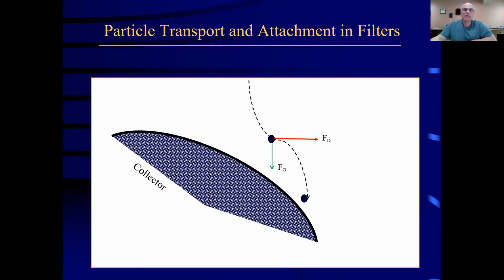Another arrow, another vector working against you, would be the electric double layer that exists between all particles in suspension. This electric double layer is what helps keep things in suspension, helps make suspensions of particles. And our job is to get in and get that very stable suspension that exists in Mother Nature and destabilize it. If we can destabilize it, we can strip away or at least make that arrow smaller so that it doesn't work against us. If we don't destabilize that water, those forces are going to work against us and make it very difficult for these particles to ever settle. In fact, true colloidal particles will suspend themselves in water and stay there for a very long period of time. We're talking days and weeks if you don't do something with that.